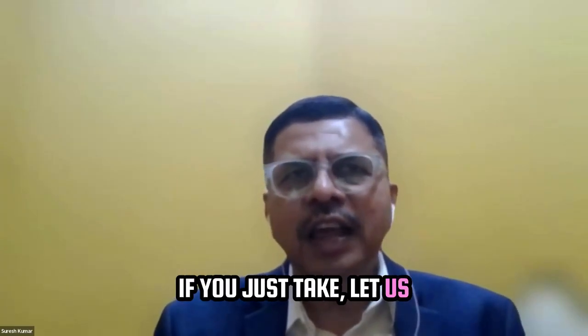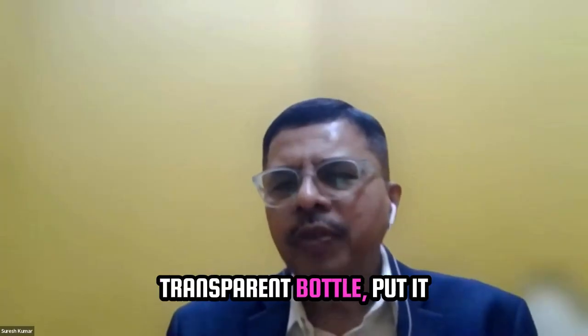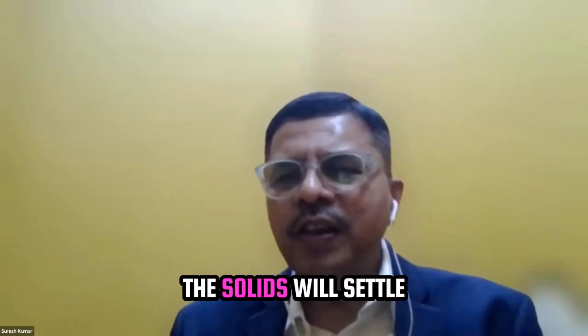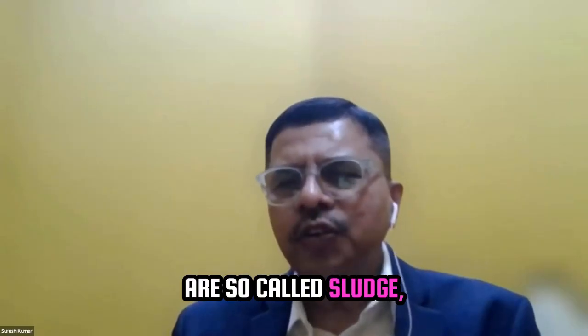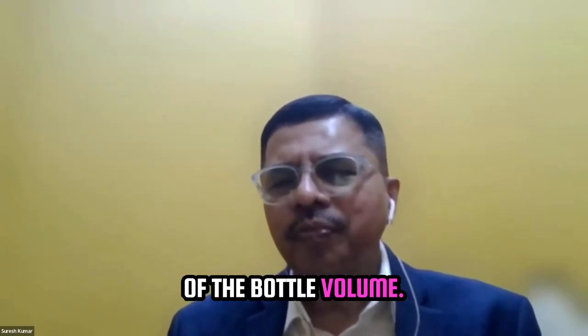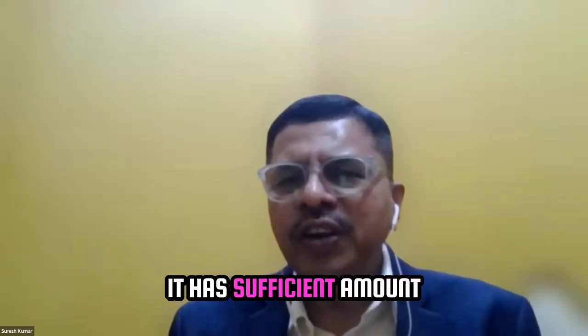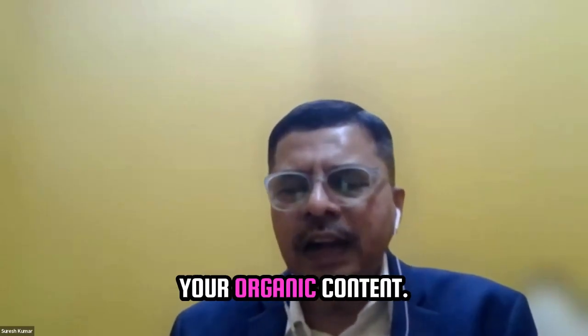If you take the aeration tank sample into a 1 liter transparent bottle and put it aside for 30 minutes, the solids will settle down to the bottom. The volume of these solids, the so-called sludge, should be 1/3 of the bottle volume. That means the system is working healthy. It has a sufficient amount of bacteria to consume all your organic content.